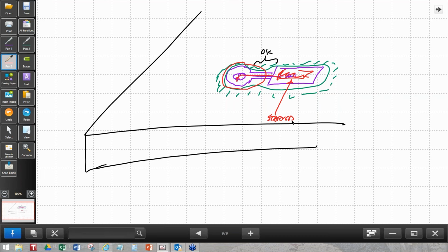You have to take the component off, clean it up, then put the conformal coating of some kind or epoxy blob over the hole, put the new part back on, and then resolder. So this gets to be fairly difficult.